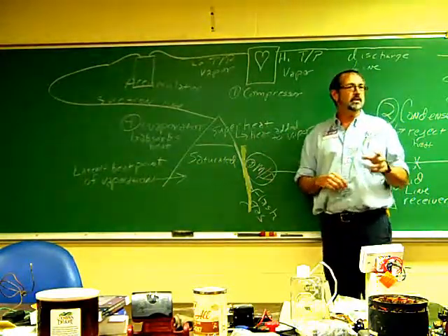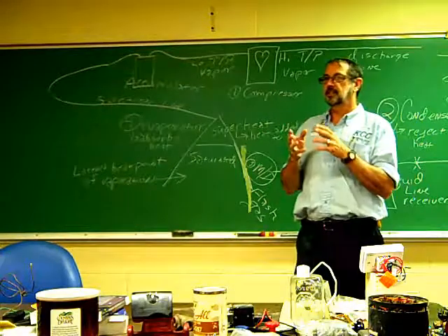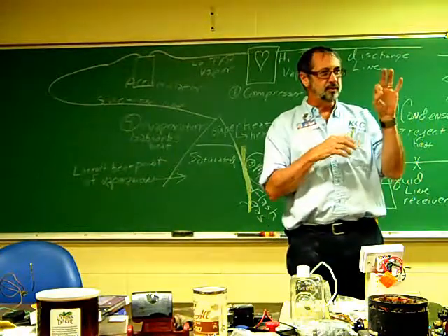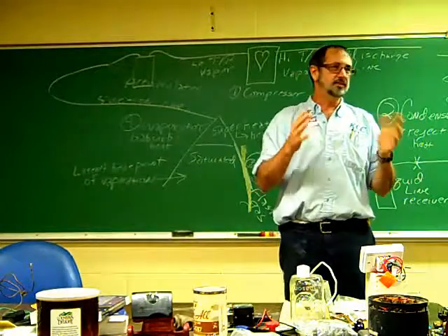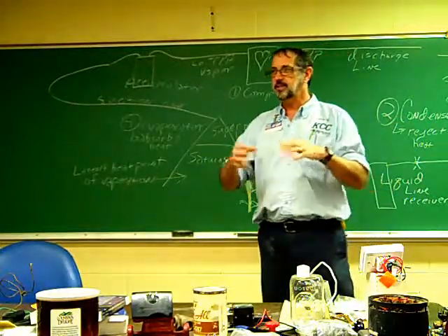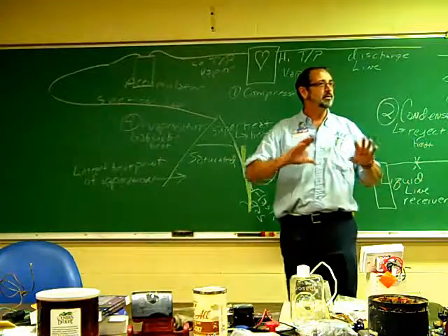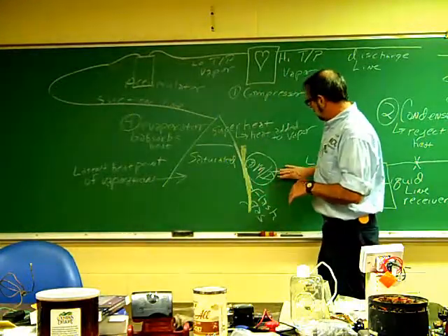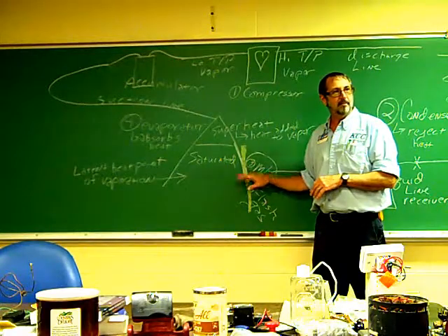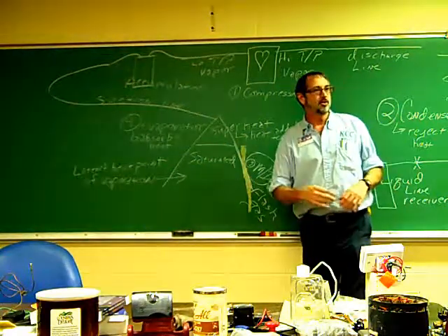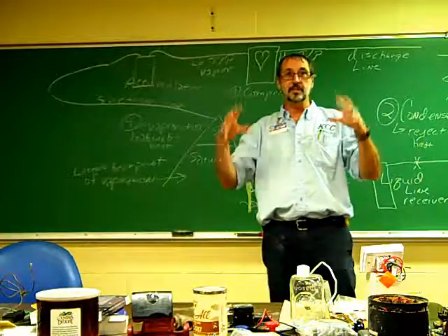Metering device. A metering device is an engineered restriction in the flow of refrigerant. It takes a little bit of the liquid in, it has a tiny, tiny little opening. It just kind of depends on what type of metering device. Again, we've talked about 7 of them when we go through that chapter. But it restricts the flow of refrigerant. When it comes out into the evaporator, we'll talk about that in a second, we're going from a real small space to a real big space.